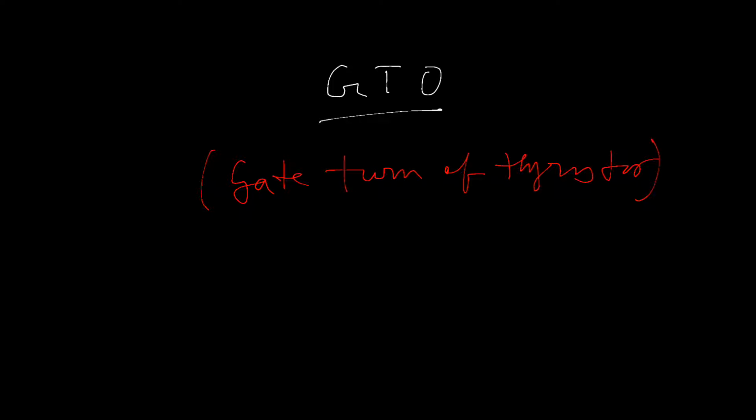Actually, a conventional thyristor can block high voltage in the off state and conduct large current in the on state with a small on-state voltage drop. It can be switched on by the gate signal, but the gate loses control once the thyristor is triggered. So the thyristor goes back to the blocking state only by reducing the forward current to a level below that of the holding current. This is a big problem during switching mode operation.